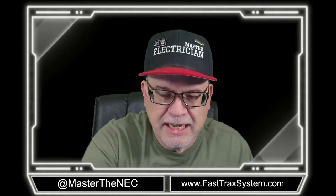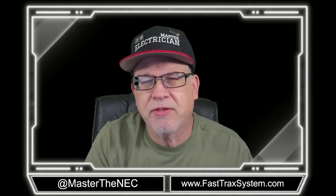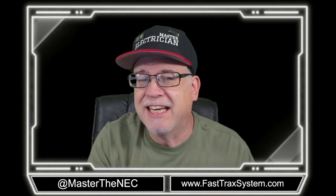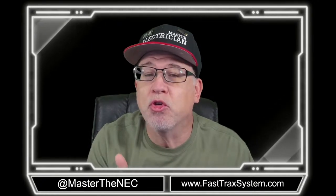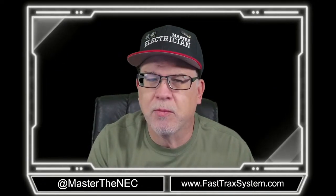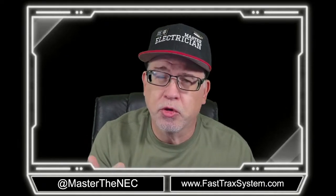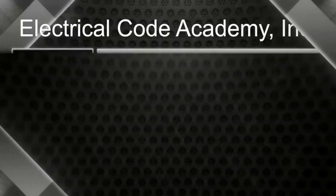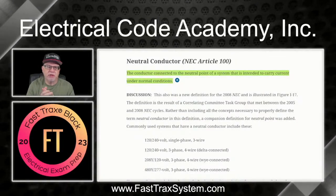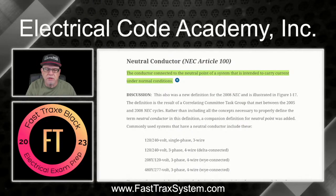All right, so let's get into it first. It's important that we learn definitions, because since the 2008 edition of the NEC, we've had a definition of neutral conductor as well as a neutral point. That's the point on the system where the neutral conductor is connected. So that kind of derives the neutral conductor. Okay, so here we are. These are definitions out of the 2023 edition of the National Electrical Code, and this is out of our grounding and bonding series.